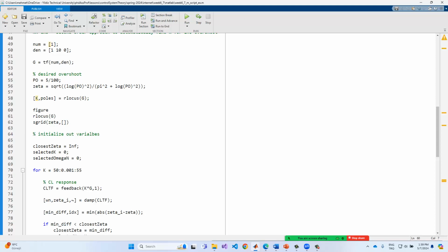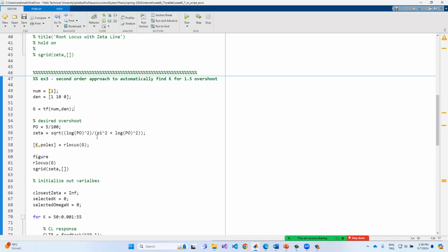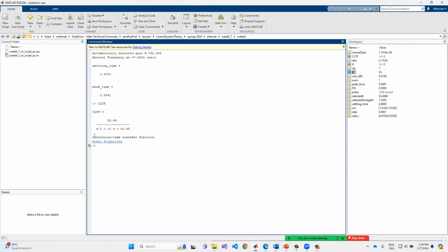So in this domain, we have the closed-loop transfer function, CLTF, as equals to the what? This one. This is the second order. And so, you just remember that. In the second order system, we can approach the second order approximation with omega n square divided by s square plus 2 zeta omega n s plus omega n square. And so, which means that we can set the exact settling time, exact peak time, exact steady state error.